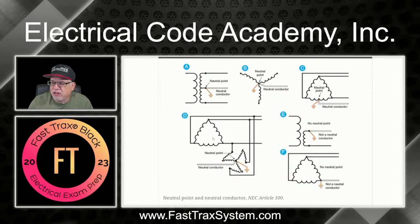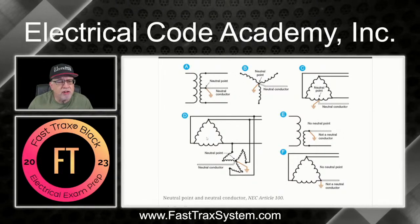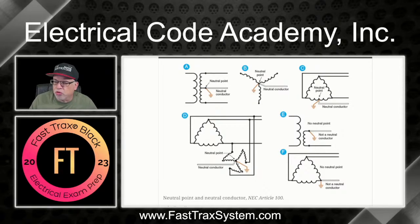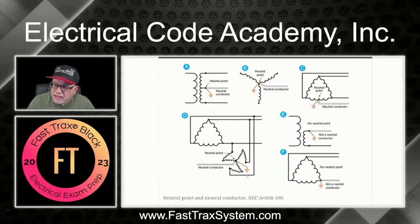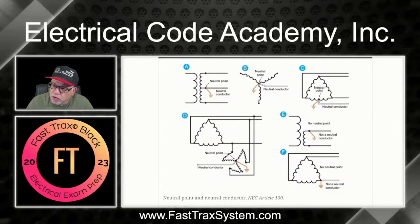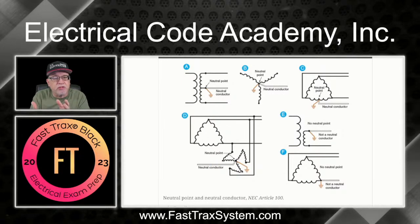Now, D is an example where we have a delta system here, and this is obviously an ungrounded delta. Then you have connections here that come down and hit a zigzag transformer. And in this one, there's a neutral point here. And then this system is intentionally grounded, creating this neutral conductor on this system. Now, notice this is derived from an ungrounded system. Right? So this is how you can create it as well.